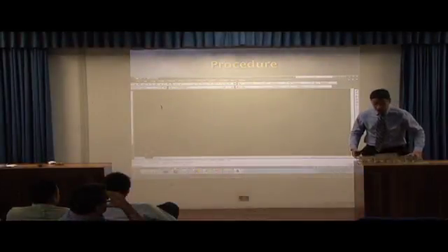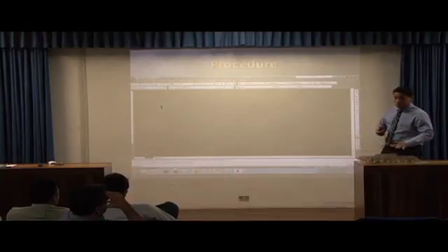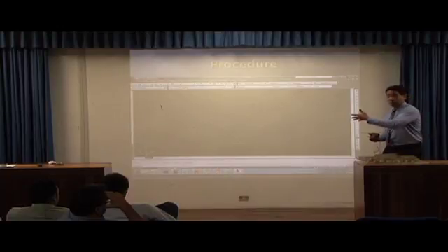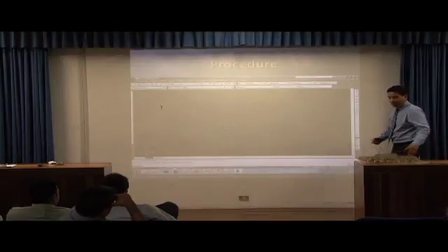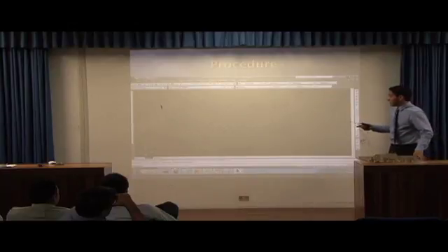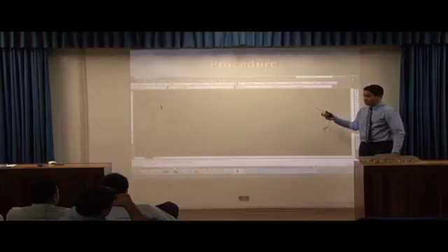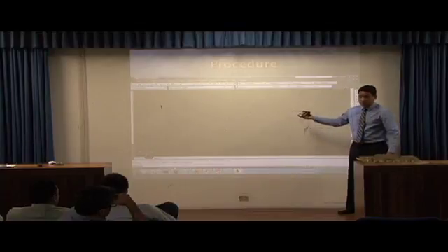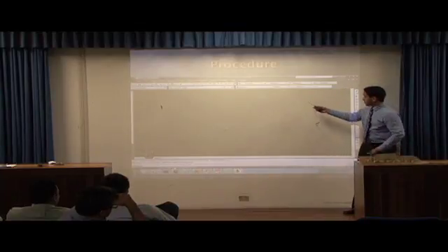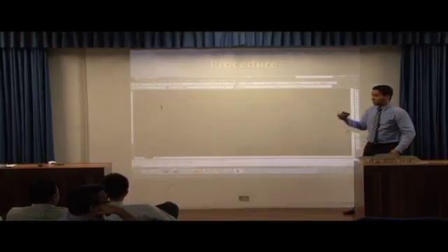This is a foundation of a machinery room. We want to make this in a program. We're going to use the finite elements using the software SAP 90. So we first start making the base. As you can see on the screen, the length of the base is about 975 centimeters. The spacing between each frame is about 75 centimeters. We have 4 stiffeners, so we put another ones imaginary to help us in the analysis.